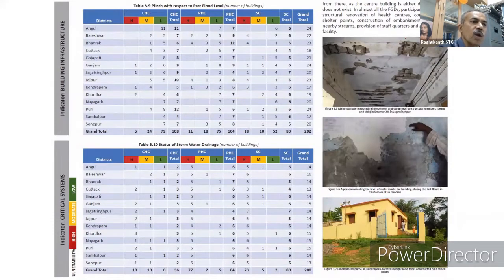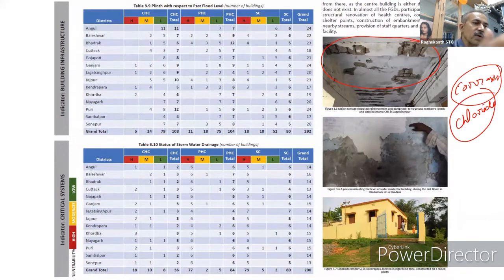You can see the whole of the hospital buildings are full of corrosion actually. This is the most important thing which we have seen. The main issue is corrosion, and it is all chloride corrosion. This is what we have observed. Of course, the loads are all perfectly fine, but there are some places with problems.